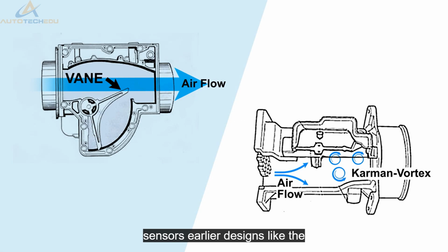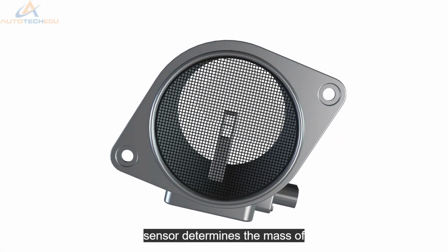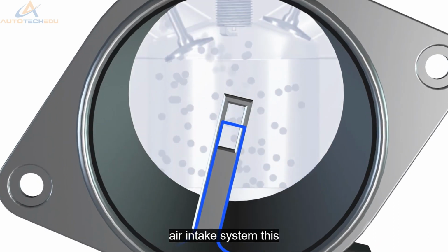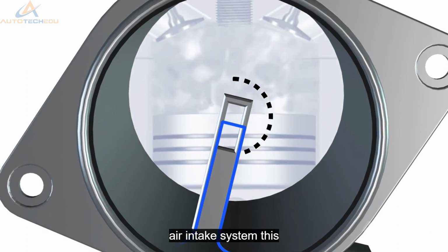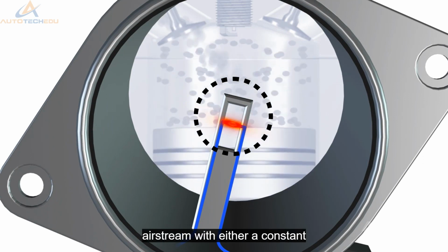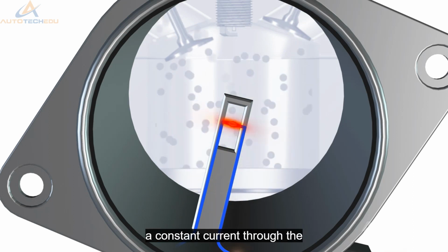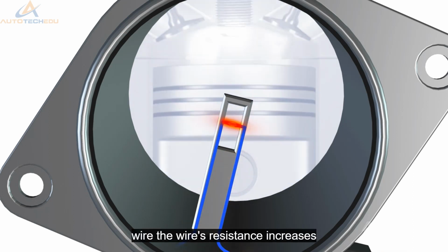Earlier designs, like the Vane and Kármán Vortex, only measured the flow of air, not the mass of air. A hot wire sensor determines the mass of air flowing into the engine's air intake system. This is achieved by heating a wire suspended in the intake airstream, with either a constant voltage over the wire or a constant current through the wire.